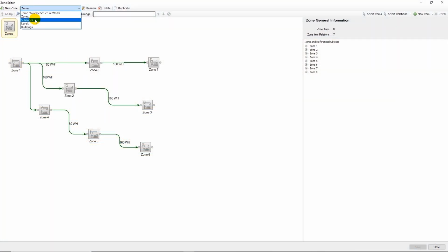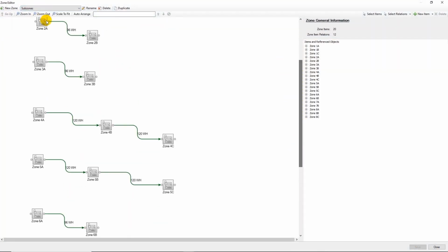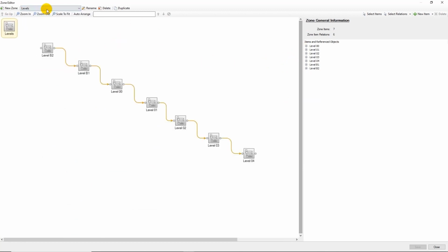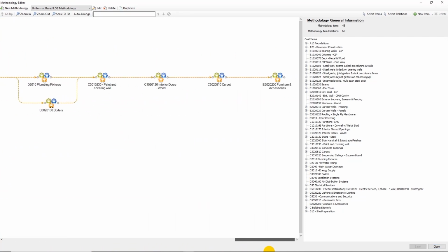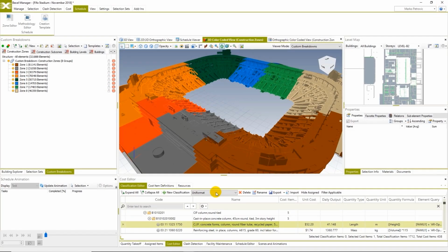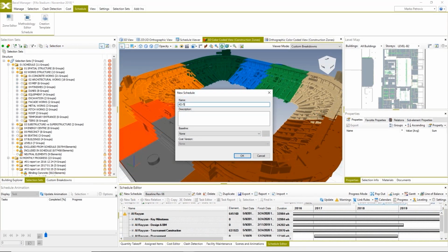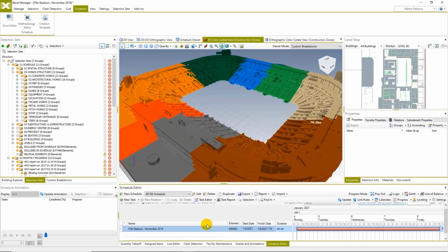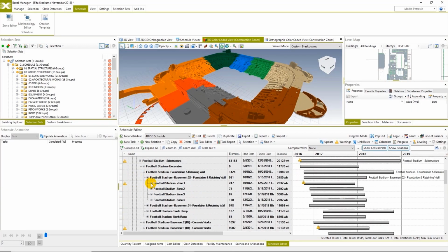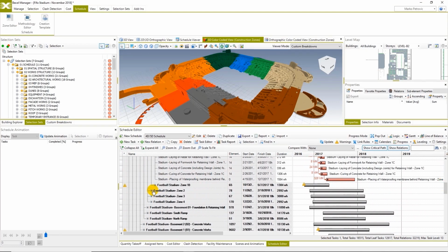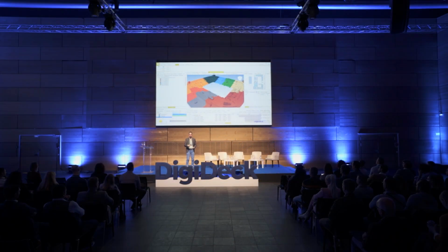Once we have it, the planner makes a schedule hierarchy, the template, and the system generates intelligently the entire schedule with all respective tasks and relations between tasks. So just to simplify the process, if you, for example, specify that first you want to execute column, then beam, and then the slab, you just have to tell the system that information only once. The system recognizes where these elements are in your 3D file and copies all these relations through the entire building. So in that way, you're going to get the entire schedule created, the entire work plan.